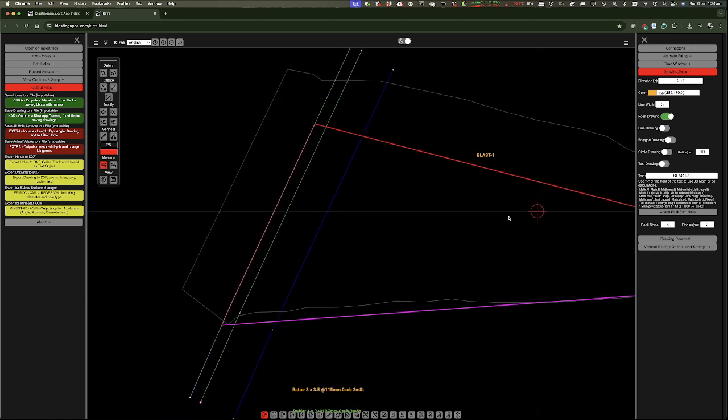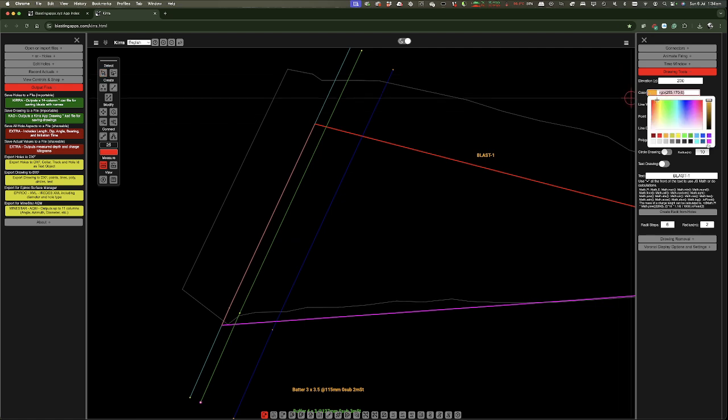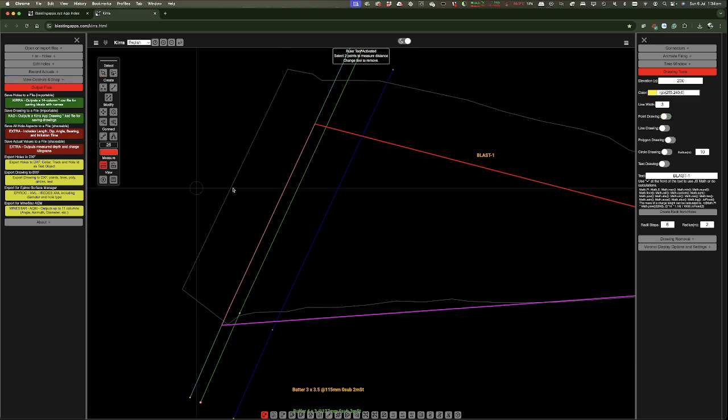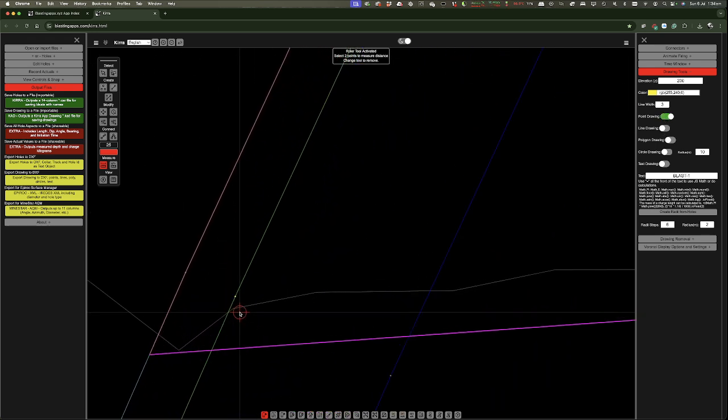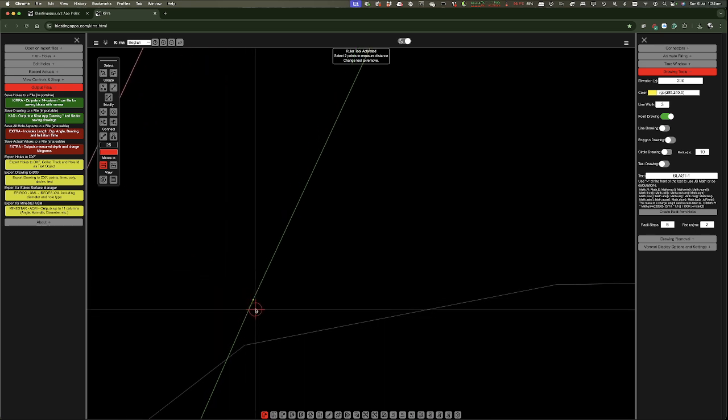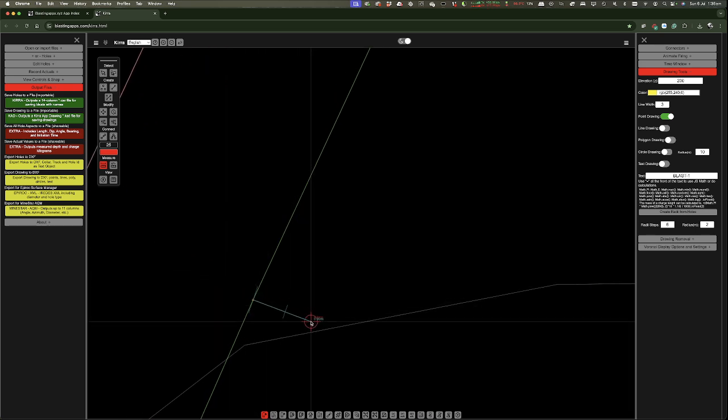Well, we would generate some points for starters, and we'll mark these as, what should we do our drawings as? Yellow. Right? All our stuff will be yellow, and we'll turn on the ruler and the point, and that way we can use the ruler from this point here, so we can snap and we can say, all right, we want a meter offset.